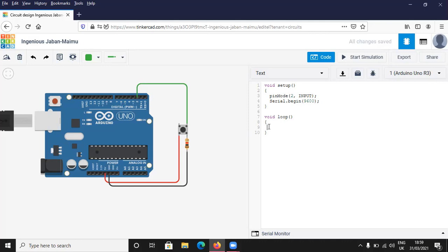So next, we need to read the value here. And please know that this will model so many devices that we deal with, very many. I'll be able to talk about that when we are done with the experiments, what it's modeling, the button switch. So from the programming part, you read the value: int A, that's a data structure, and then digital read 2, because you're supposed to be reading from 2. That's why we have connected our port.